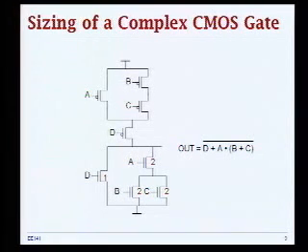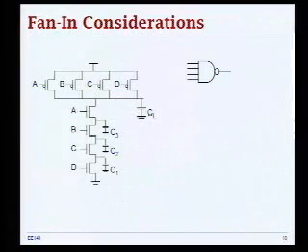And then for the pull-up network it is basically the same strategy. You know that this one is in serial connection with the rest of the network, so you double that. And then for the other transistors, you also have basically the same value if only A and D are turned on. So it's basically the same as your NOR case. And then you have these other 2 that have to be further upsized because they're in series with each other. Okay? Does that make sense? All right.